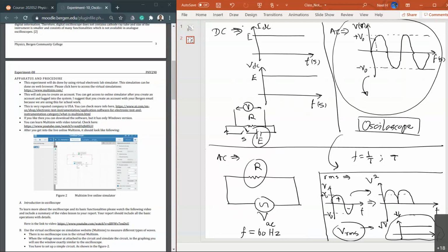That kind of observation you can't do by just using the multimeter. So that's one of the important advantages. And also you can do other manipulation. If you add another resistor, another capacitor, for example, later when we talk about capacitor and then inductor, all of them together, an LCR circuit, the digital ammeter or digital voltmeter or the multimeter itself isn't useful at all. So we need the oscilloscope to see what's really happening inside them, particularly if we have AC voltage applied. Those are the advantages and usefulness of the oscilloscope for this kind of circuit analysis.